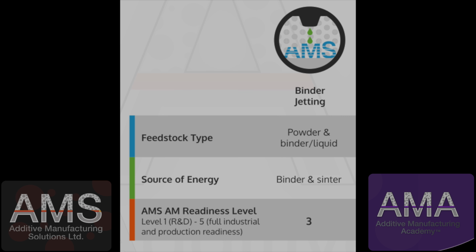The mass market of additive manufacturing technology seems to be most likely to be penetrated from binder jetting. That's because it was envisaged that this technology will be able to produce parts very quick, cost effective, and therefore compete with mass produced castings. It would also be envisageable that binder jetting would be able to access markets like the automotive market, which some other additive manufacturing technologies would be unable to penetrate just due to the costs and economies of scale.